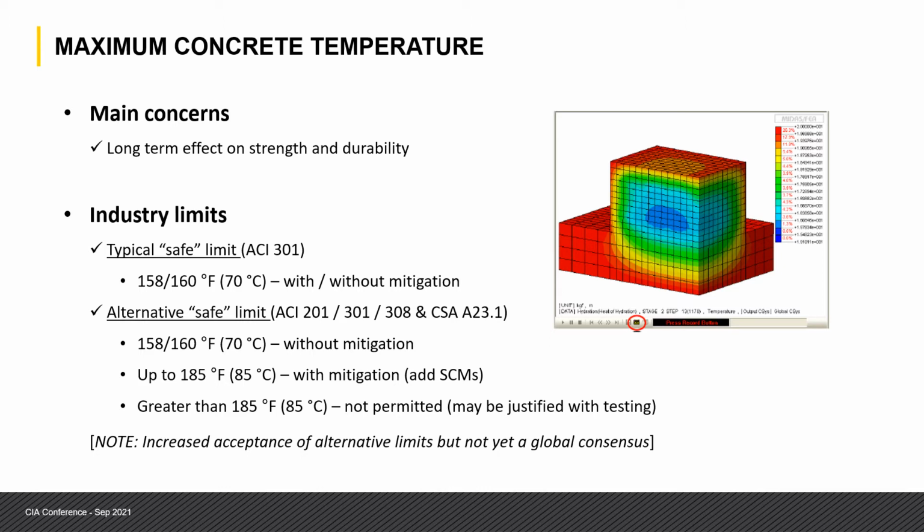Now, the standards recognize pretty well that greater than 85 degrees Celsius is not permitted. In such a case, you have to justify the DEF durability with testing, and that's something that has been provided given the research available and the results and the different options, but there's no consensus on exactly what test method can be used. The alternatives for acceptance are provided by ACI, and people can use them given the materials available that they can provide for mitigation of higher temperatures.